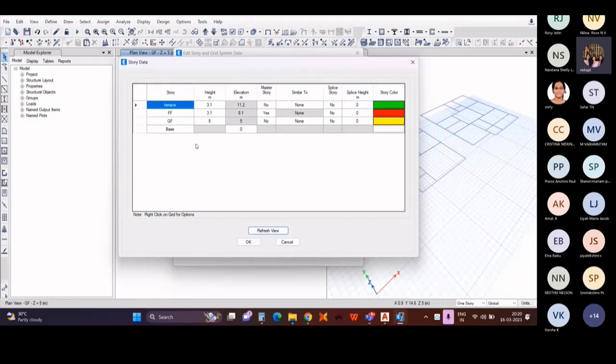So in this particular villa, the foundation is pile foundation. So we need to enter the depth of fixity of that pile. Depth of fixity as per code is 10 times the diameter. So 10 times the diameter, say the diameter of a pile is 500 mm. So 500 into 10 is 5000. So 5000 mm is 5 meter.